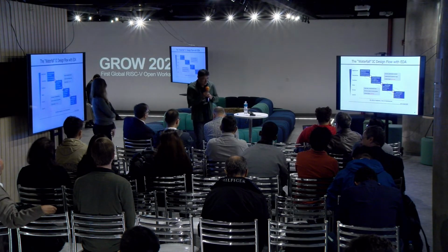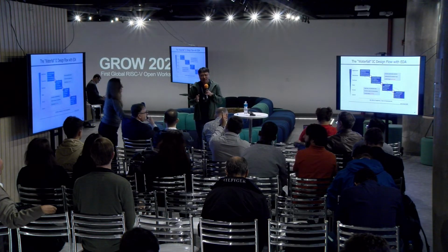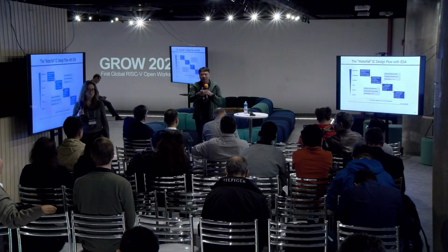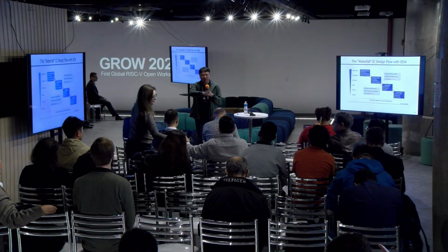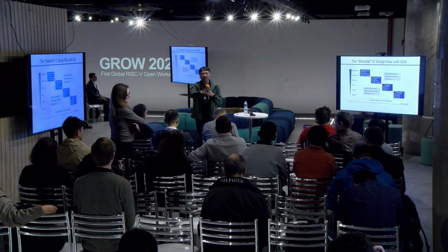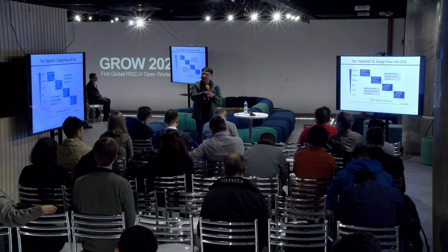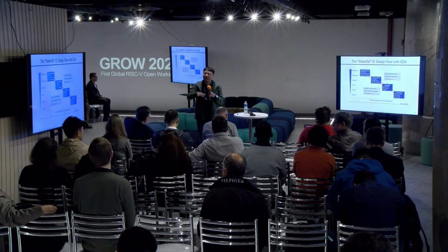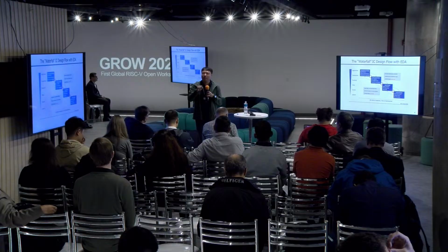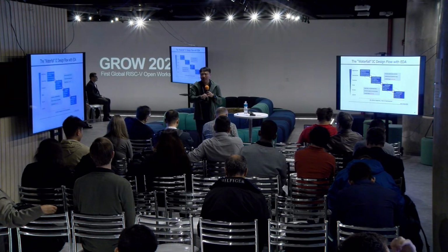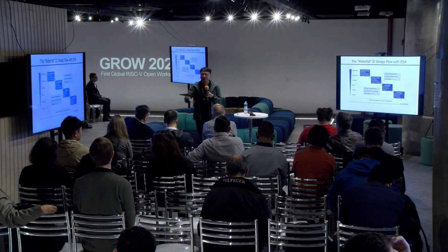Sure. First of all, one thing I keep emphasizing is that LLMs are not enough for IC designs. If you have a circuit and give it to an LLM, it doesn't know which one is going to be the critical path, because it doesn't have the concept of a path. You have to analyze the graph structure to get the path. So if you use LLMs alone, they won't be able to give you the correct answer in terms of PPAC optimization.